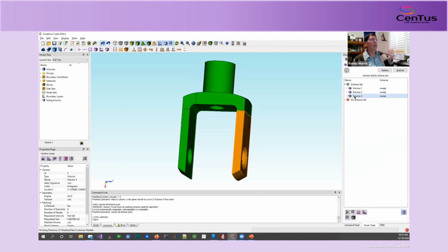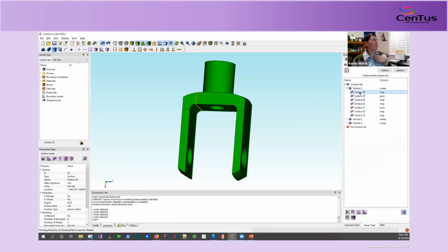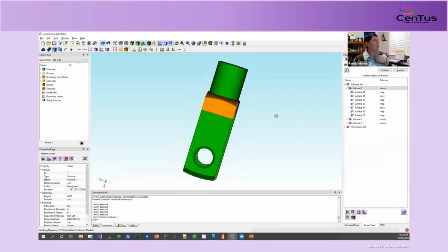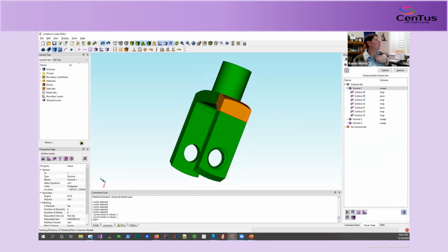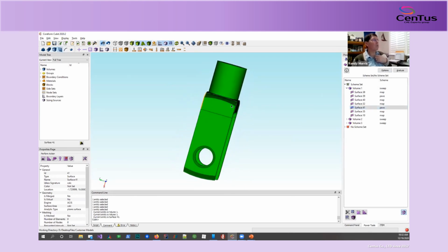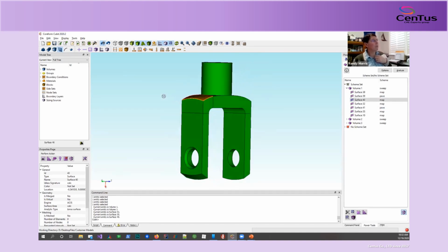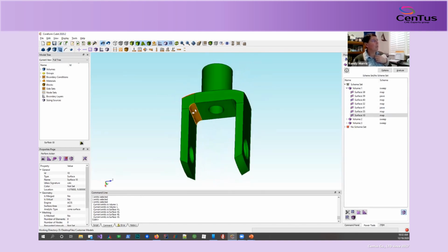And now I've got that one, and that little guy ready to go too, right? So we've got map surfaces there. We're going to pave that surface. We're going to pave this surface. Sorry about those. Do this different. Pave this surface, and all of these other surfaces, as you can see, the linking surfaces will be mapped. It's exactly what I would expect, including that little guy down there. That's logically four-sided, so we can map it.